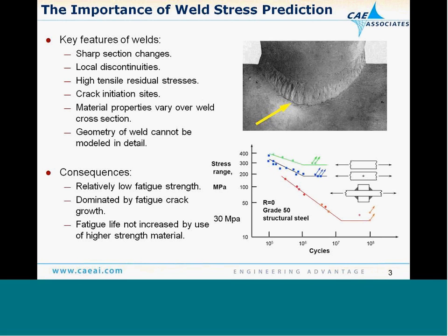And to quantify that, if we look at the condition of S-N curves in terms of fatigue representation, and we take just a flat bar, in this particular example, the endurance limit, or the limit where we have infinite number of cycles, is a stress level of about 300 megapascals. If we take the same bar and put a small hole in it, we see that we get a reduction in fatigue strength down to the area of 200 megapascals.